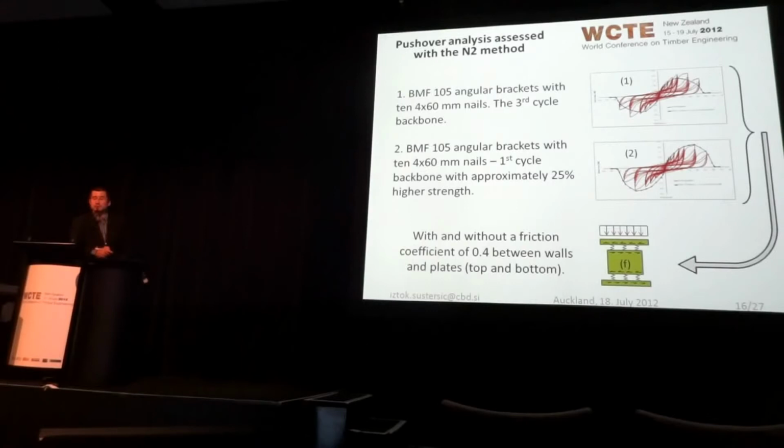Former analyses done on cross-lam were done with walls made out of several narrower, adjacently connected walls, and the Q factors for that were about 3, 3.5 and so. Considering we have here monolithic walls which are larger and have less dissipation areas because we don't have the vertical joints, this seems to correlate. However, of course, there are wall analyses that need to be done.